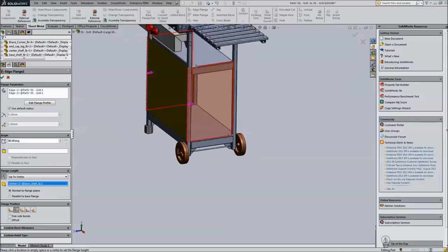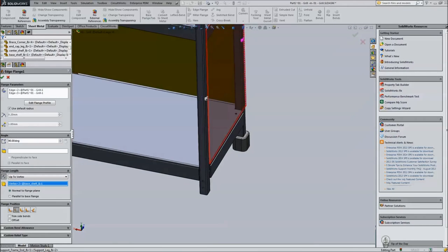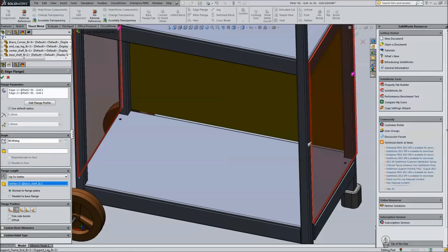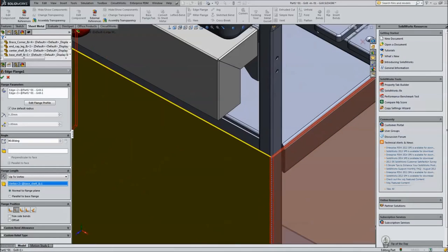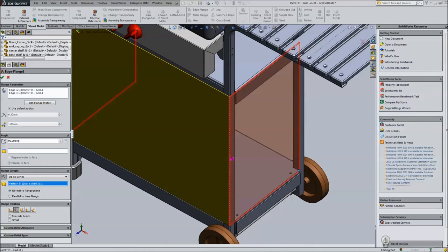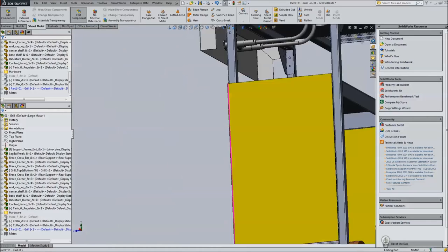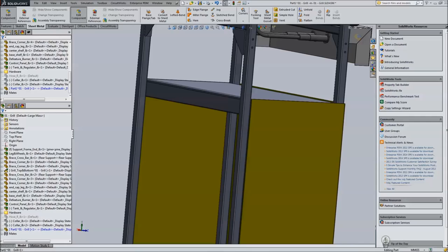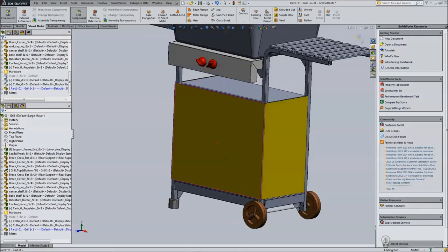So ultimately, in the end, I have these side flanges. I want to put a return flange here on this side, same on the other side. On the bottom right here, I want a return flange coming in. And up front, I'm just going to have a return flange coming in and down afterwards. All right, so I'm just going to hit OK here. Here's what we have so far. And you notice I put those two flanges in by myself, all within the command.